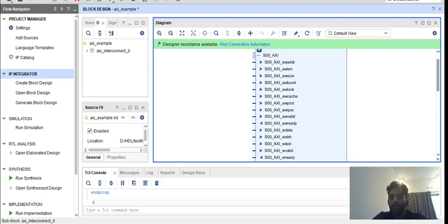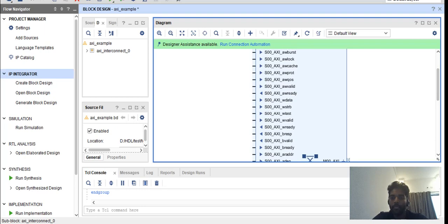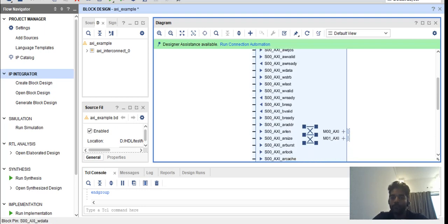Similarly, if you look into the naming convention for the data, it's just write data, and strobe, valid and ready, just 5 signals here. Just ensure this handshaking is happening properly and send the data accordingly in that case. Okay, so you have to wait for the ready from the slave. If your slave is active, you just have to monitor this ready signal. Whenever the ready is available, you can start sending your valid data. The address has been already issued, and the burst type is already been issued.